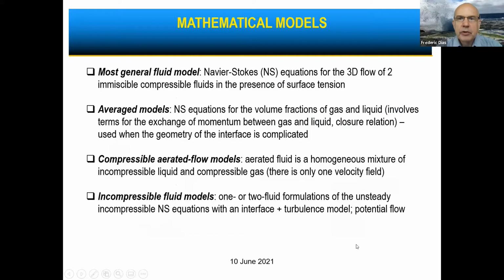Okay, so when you want to study this slamming, there are several mathematical models that you can use. From the most general one, which is the Navier-Stokes equations for the 3D flow of two immiscible compressible fluids in the presence of surface tension. Then average models, where the Navier-Stokes equations now are for the volume fractions of gas and liquid. And so this is used when the geometry of the interface is complicated.